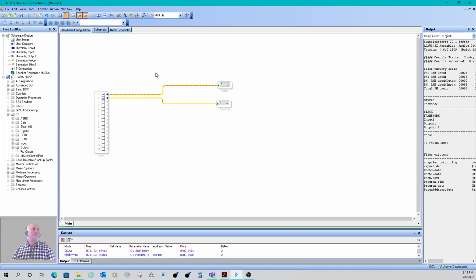There's a bunch of places things can go wrong. So you have to ask yourself, for starters, the very basic stuff. Do I have it plugged in? Is there power? Am I communicating? Because there's audio into the DSP and audio out of the DSP that could be going wrong. There are many other settings that could be going wrong. There could be clocks missing. But the very basic is, are we communicating with the DSP?